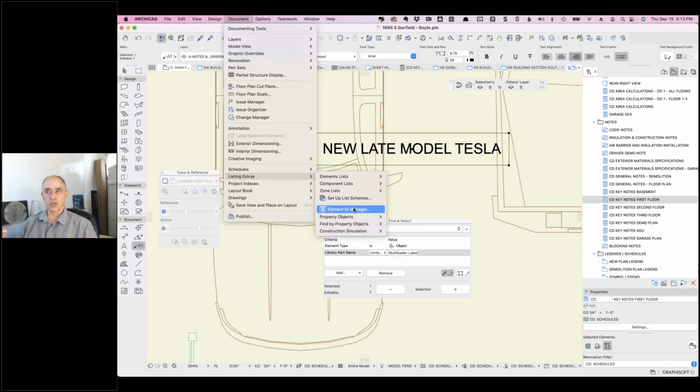The short answer is you can select them one after another, like go around the building clockwise, for example, shift click, shift click, shift click around, then do the Element ID Manager, tell it how you want it to be numbered and even where it starts, like maybe you're on the second floor, so you want them to be window 21 through 28. So you can just tell it where to start, and then it will number it based on that. So in the case of the keynotes, you could select keynotes that are placed on,